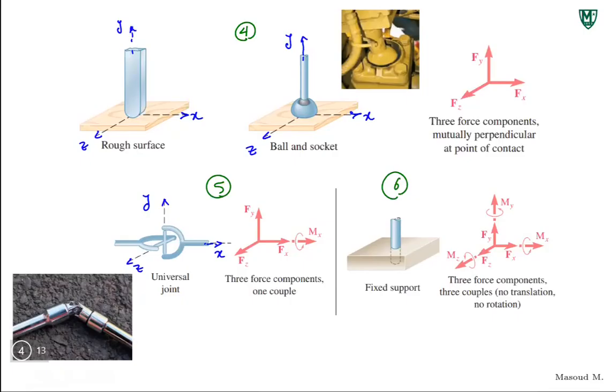this works. But if you look at rear wheel drive cars, the way the power is transferred from the engine in front to the back, it's especially easier to see them in trucks because they're a little higher, and you can see underneath. You will see these kinds of joints. They are great because we can transfer the rotation, in that case the torque, of the engine to the rear wheels of your car in the back, without being worried about this shaft breaking.